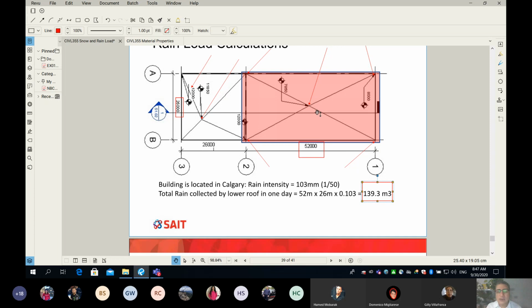I want to say, guys, I'm not stopping here. It's going to be a little off topic, but it's very important. How do we slope our roof? There are two methods. One is to make the structure itself, like the beams and columns, of the same height, but change the depth of the insulation. And this will give me my slope.